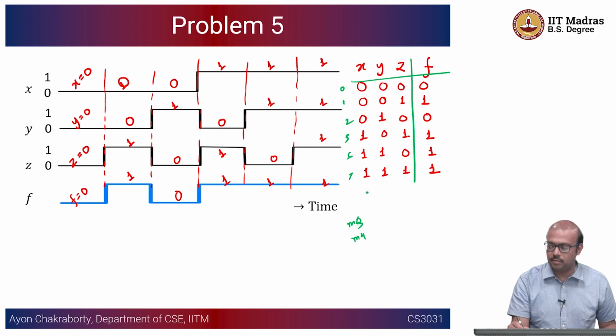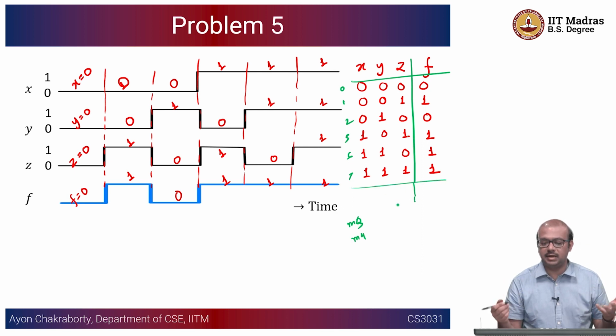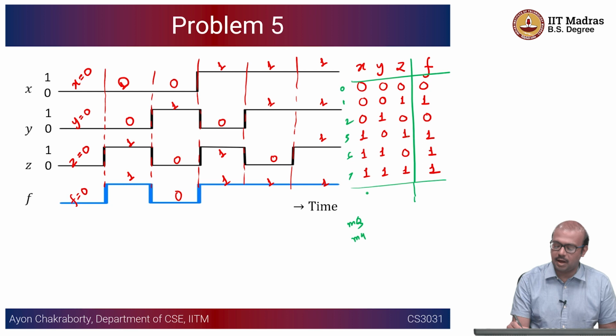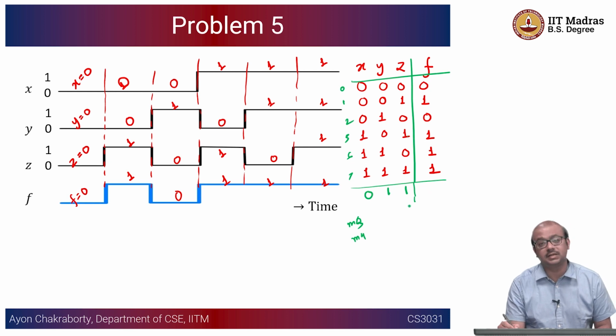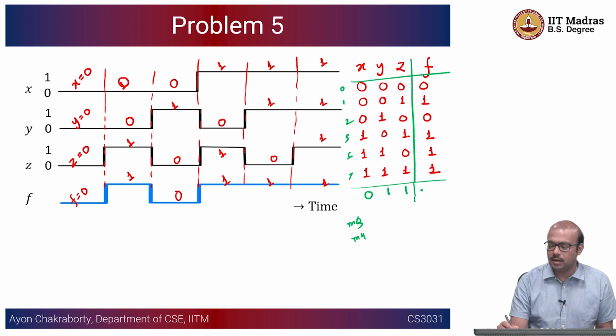So you have to define what these inputs are, or they might say you do not care about any other inputs, the other inputs are redundant, not really important for your system. They are typically called don't cares, right? So if you have 3, which is 0, 1, 1, the output you really don't care. If you are solving a function minimization problem, you can treat it as either a 1 or 0 depending on whether you can group these elements together nicely, in a K-map, for example. So 0, 1, 1 can be treated as a don't care condition.